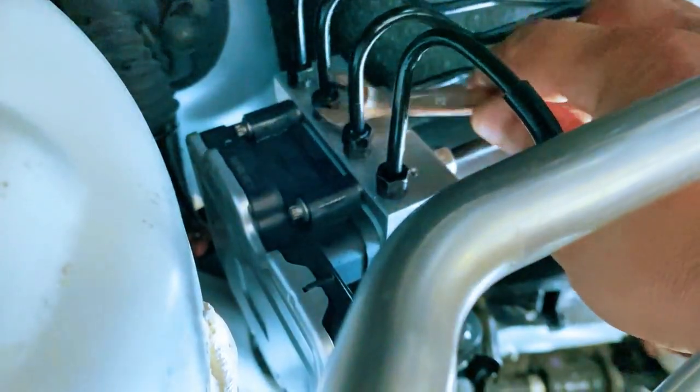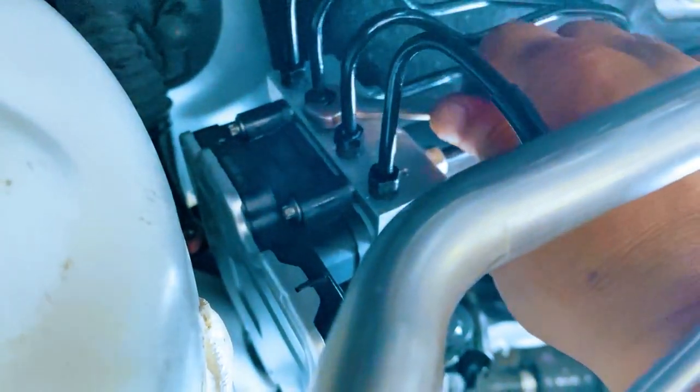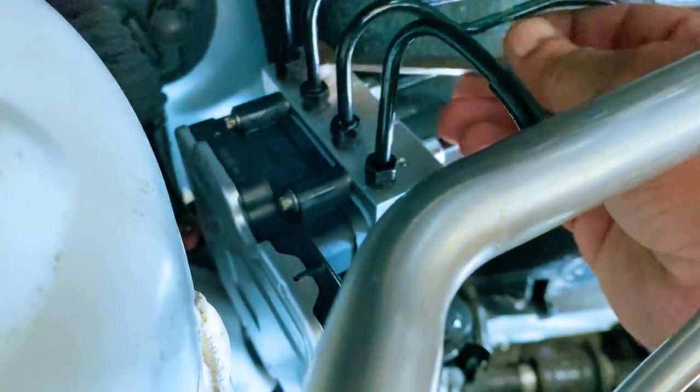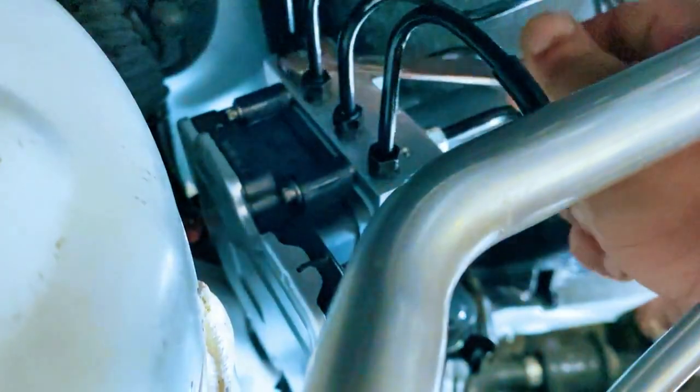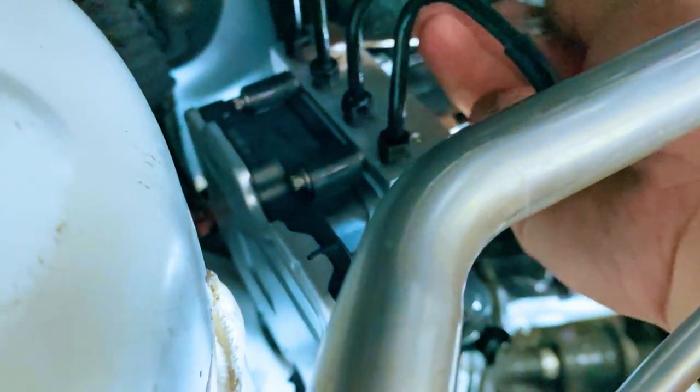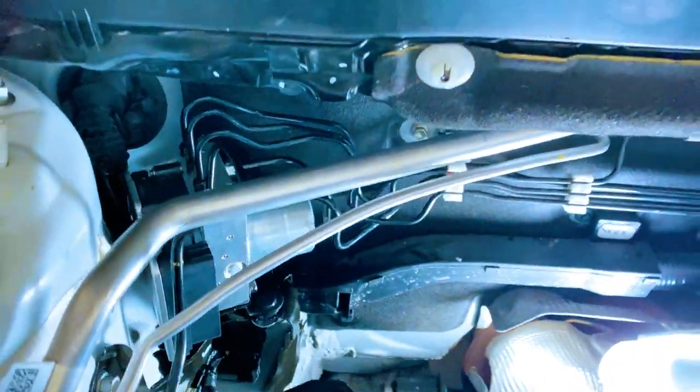Use the correct flare nut or union nut wrench. Do not use an ordinary open-end wrench if you can avoid it. A damaged flare nut can become extremely difficult to remove. Also protect the surrounding components from brake fluid. Once the brake lines are disconnected, protect the open ports and lines from contamination.